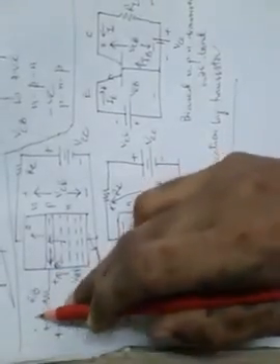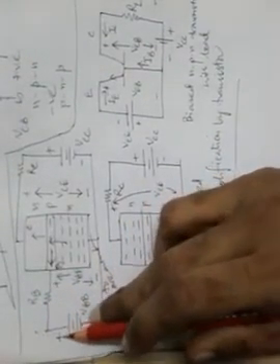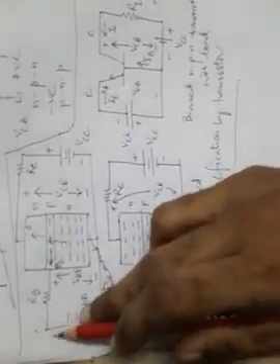But since there will be some amount of recombination with the holes, only a few free electrons will recombine with those holes in the lightly doped base area, and they will become valence electrons from free electrons after getting recombined with the holes, and they will flow through the base resistor RB to go inside the VBB supply, because of being attracted by the positive electrode of VBB. So this current will be called recombination current, or the loss current.